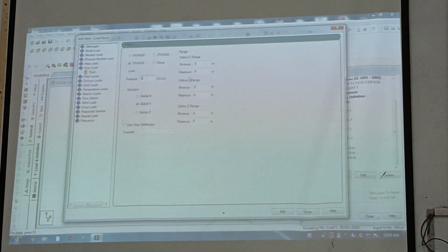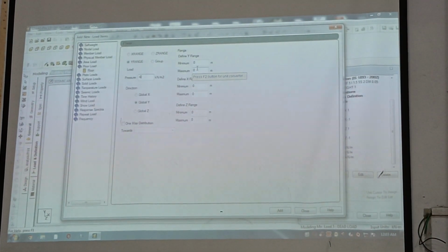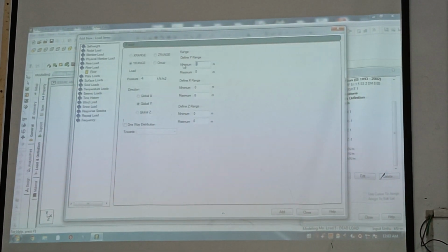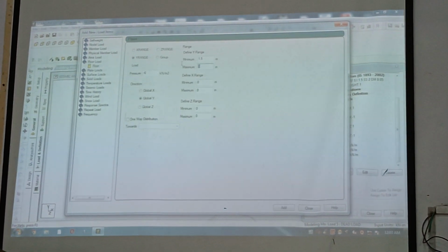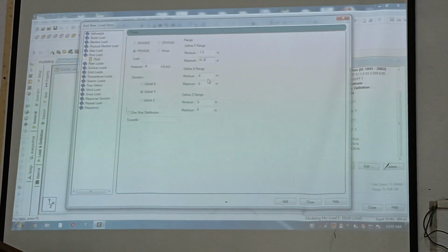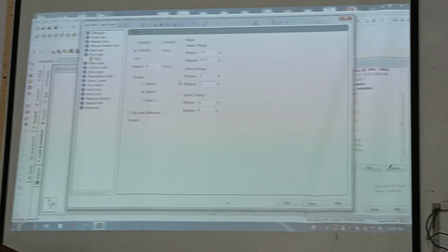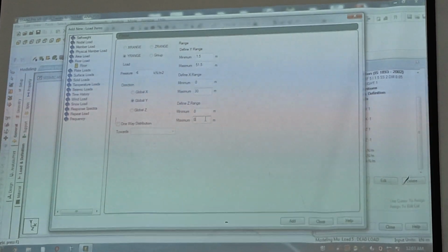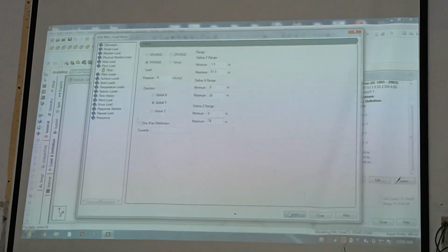Let us take it approximately, and here we have to define the heights. What are the ranges now? Y, X and Z. Minimum Y is taken from above the plinth level, so it is from 1.5 till the top floor level, 51.5. Next, minimum X 0, maximum X 30. Minimum Z 0, maximum Z 70. And then